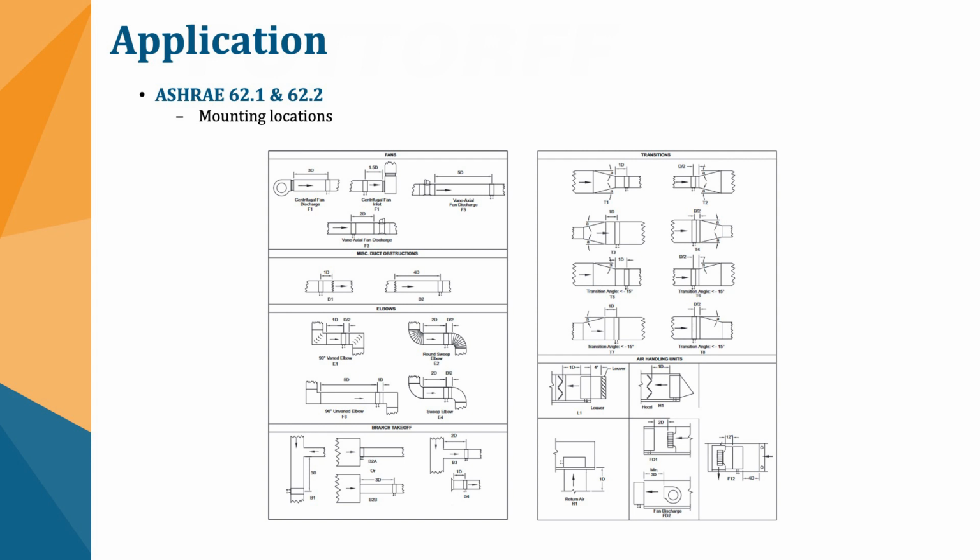So if you've got some duct device, whether it's a turning elbow that may or may not have vanes to help smooth it out, or some other device, a reducer, a fan, a T intersection, anything like that, there's going to be a generic recommendation for how far away those airflow measurement probes should be from those devices to get the best accuracy, or at least the prescribed accuracy from the different devices, as the pressure differential and thermal dispersion, which are two of the main devices, do act a little bit differently.